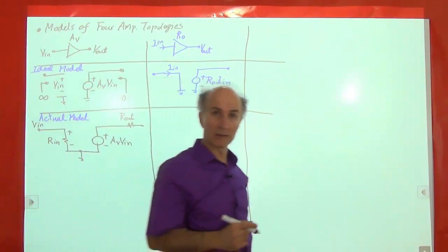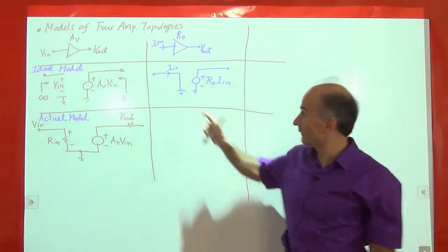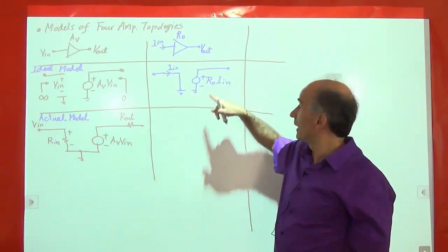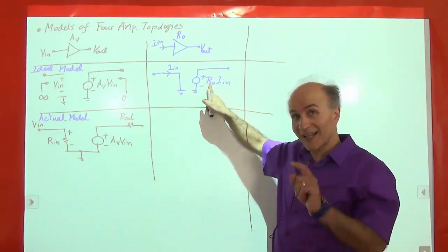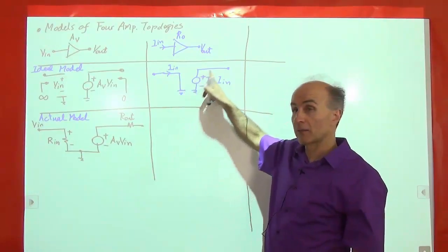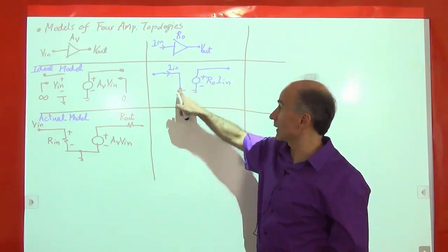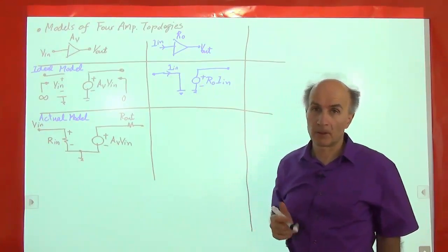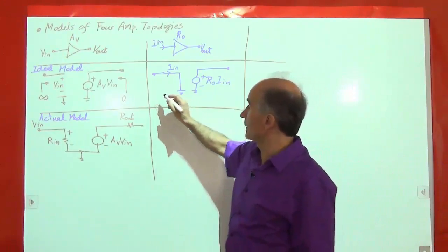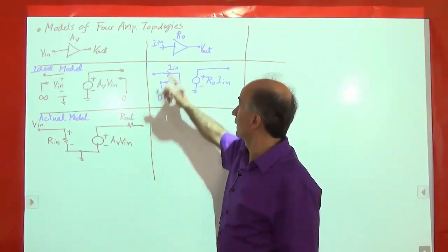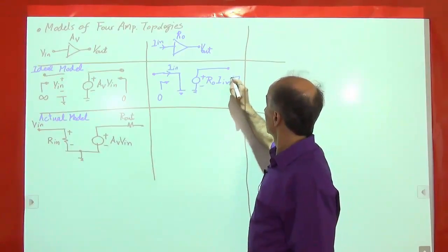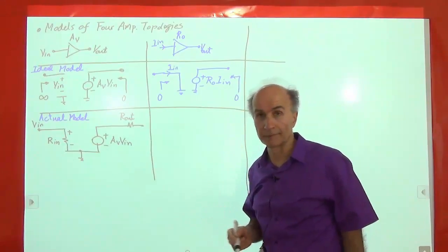This is very strange, isn't it? It's very strange, and I have a wire here just going to ground, and then what this voltage source does is it looks at the current through that wire, somehow magically, and then generates a voltage equal to that current through that wire times R0. Okay, but it's just a model. That's the only model we can build, because the input impedance has to be 0. Remember, ideally for a current sensing circuit, and the output impedance has to be 0. So that's what we get. There's no other way.